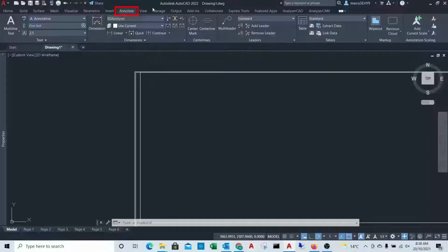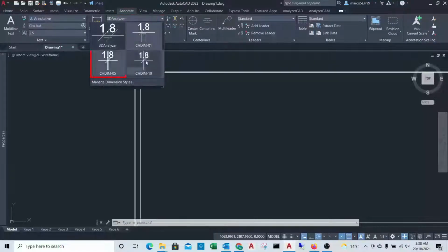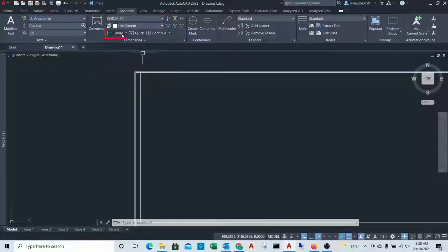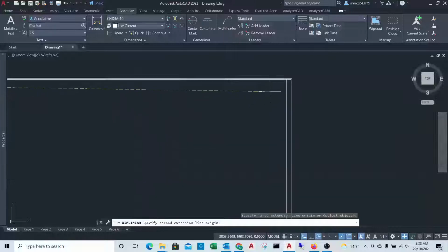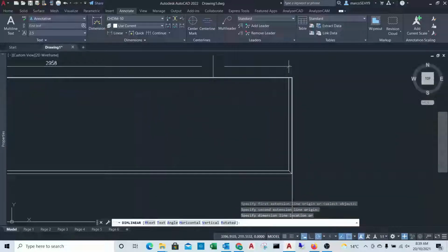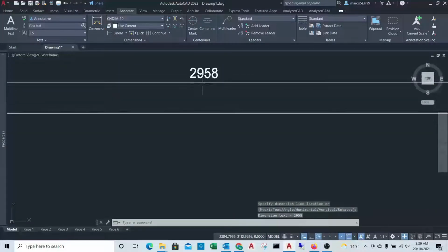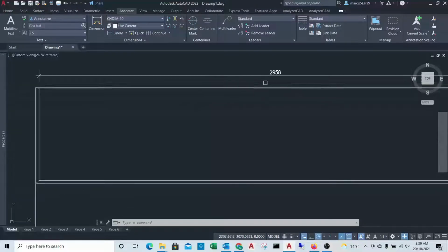We should check the overall dimension in the cabinet space to make sure they fit in the area provided. We can change the dimension style and have a look at the internal measurement between the end panels. It works out that we have a measurement that will not easily divide into 5. If you make the dimension 3 mm shorter to 2955 mm, you are going to have a dividable measurement. This also gives us a little more space for tolerance for a material variation.